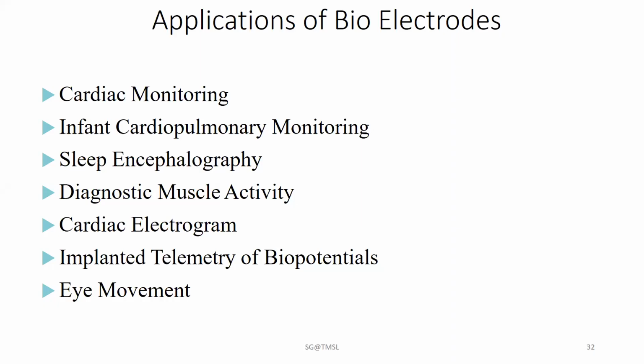Another point: in detecting surface potentials on the body, or internal potentials within it, while using pairs of electrodes for measuring differentially, it is better to use the same material for each electrode, since the half cell potentials are approximately equal.